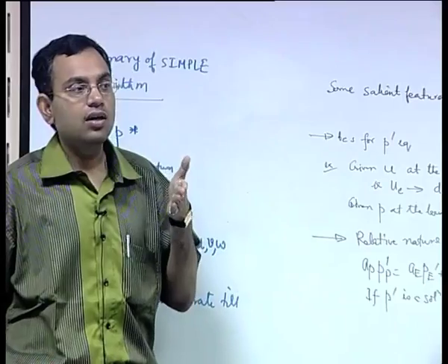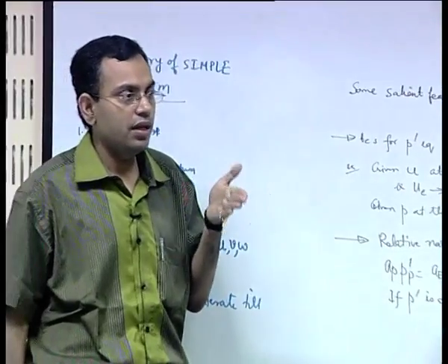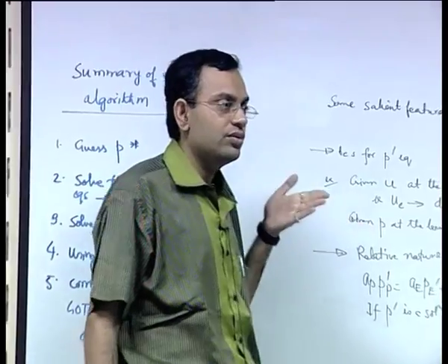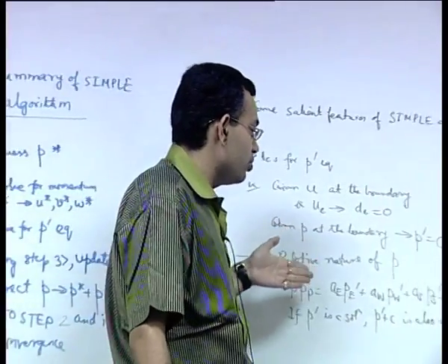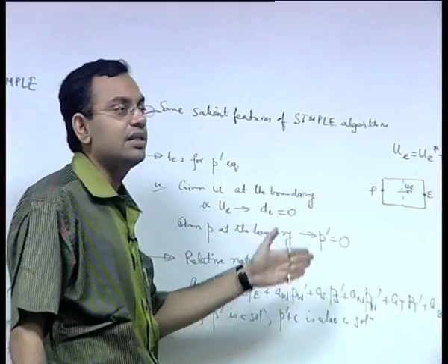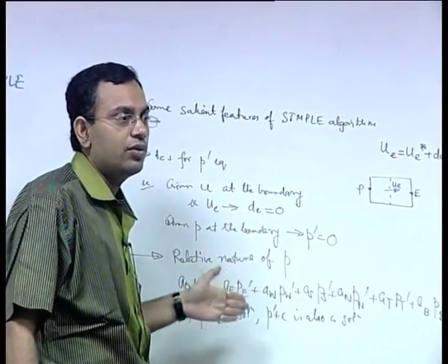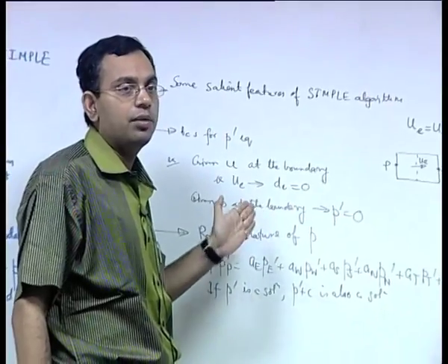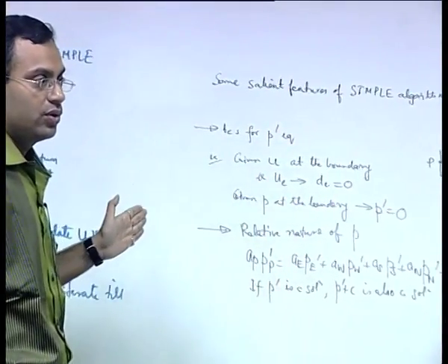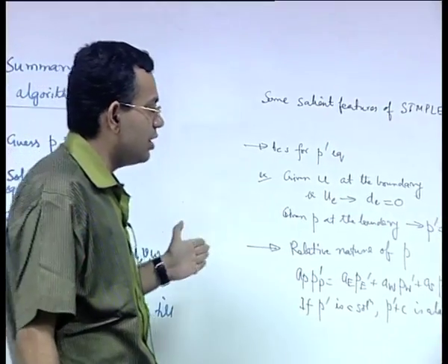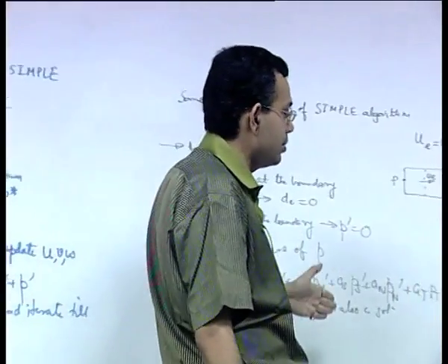and also when you have a high velocity compressible flow in a particular direction. In that case also you are adding a directionality to the equation in terms of making it a one way system, that depends on the Mach number of the flow. So it all depends on the Mach number of the flow for compressible flows.